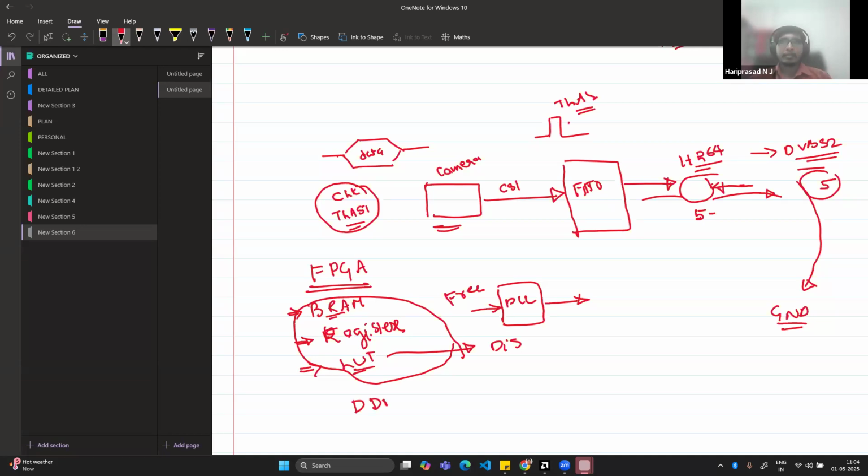This is processing memory. Let's say a stream of images is coming, so I have to temporarily store that image somewhere, process it inside the FPGA, and send it elsewhere, maybe through the network, or store it permanently. In that scenario I use DDR.